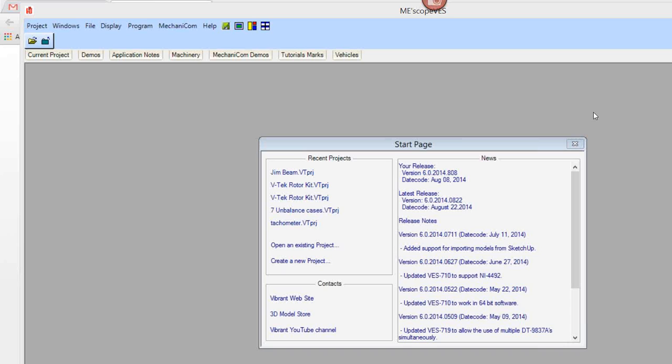This is where the animated picture comes in, where we can look at the shape in animation and determine whether it's simply what's called order related. The machine is simply unbalanced, or it's running and there are some unbalanced forces that are pushing the machine around. And so the ODS that we look at, or even the curve fit result, what we might call an operating mode shape, may be a combination of the resonance and also just the forced response of the structure. So we have to be a little bit careful with OMA data.